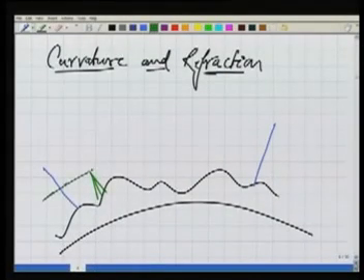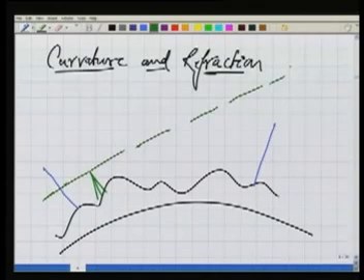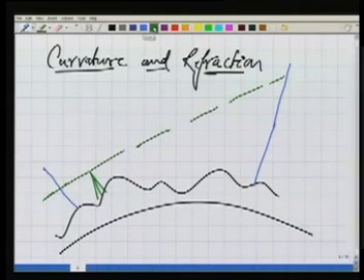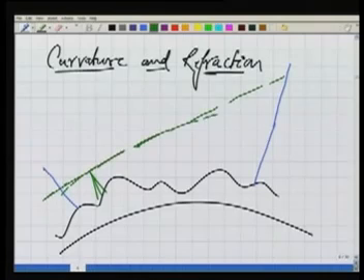So a horizontal line of sight here will be like this, which will not follow the level line. Also we know that with the effect of refraction, we don't actually observe along the horizontal line of sight, rather we observe along a curvature, and we take the reading somewhere here, RB, and somewhere here, RA.